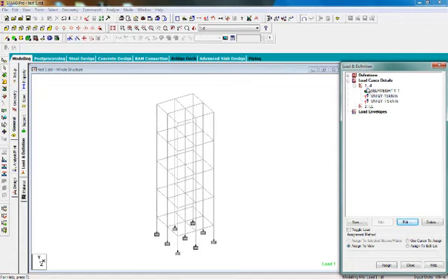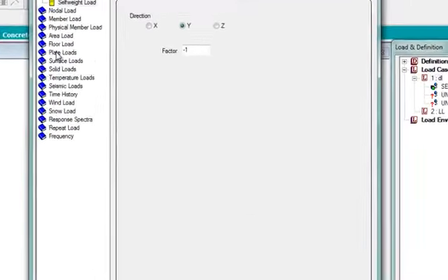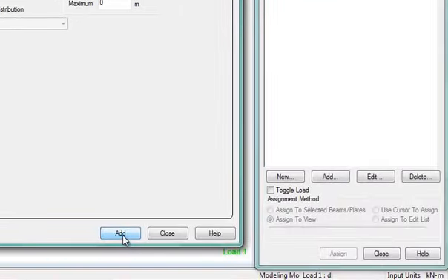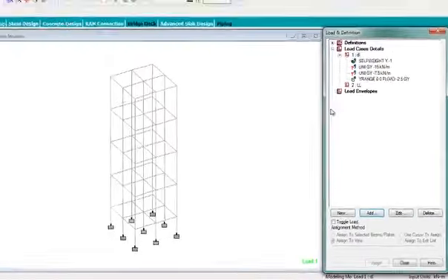So now we will also add the floor load because the slabs will also be there. So let's add it. Go for the floor load, and after calculation you may find it to be 2.5 kilonewton per meter square. It is in this direction, global Y. Add. Actually, another thing: up to now we were just writing it as add, but here you need to give a range.